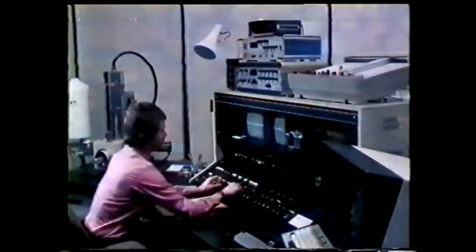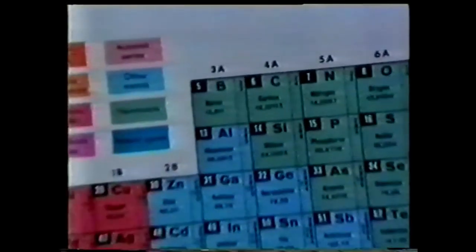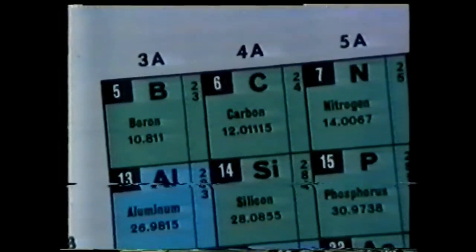Neither diamond nor polycrystalline diamond tools can be used to machine ferrous metals. This is due to a chemical reaction with the carbon which causes metal buildup. However, a new material, cubic boron nitride, or CBN, has been developed for use in these cases. It's the result of a great deal of research based on boron and nitrogen, both closely related to carbon in the periodic table, and using the same technology employed in making synthetic diamonds.